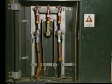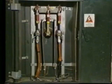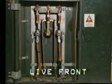With pad-mounted transformers, connections are made within the cabinet to the primary and secondary leads and also to the protective devices. In one particular type, the primary bushing terminals are not insulated so that the high voltage leads can be directly accessed from the front panel. This is called a live front design.